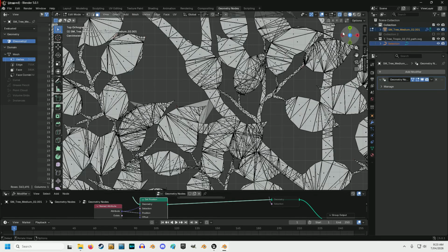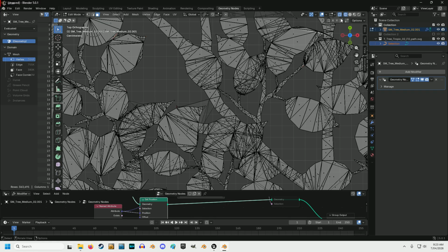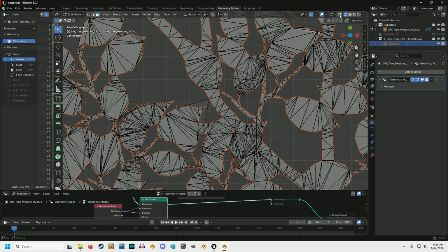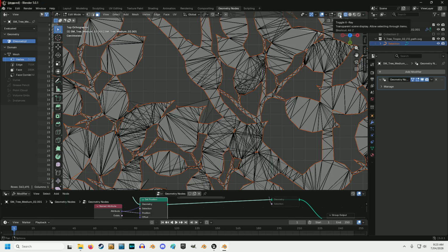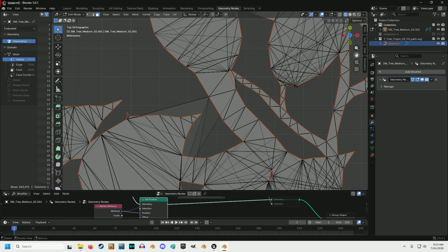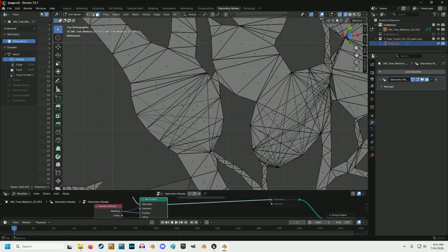in wireframe mode, having the selection selected, and then using the X-ray toggle to toggle the selection path on and off, and being in face mode, we can now select any polygons via these normals and hold shift down to select more than one, and a case of selecting those where you want to.